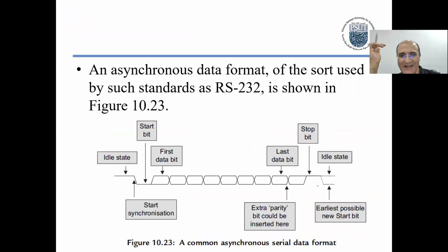So this is a standard. We call it RS-232, very common in asynchronous serial communication. Usually the line is pulled to idle, and then these are logical levels. Sometimes they can be flipped: the high could be low voltage, and the low is high voltage. You don't care about it for now. So usually you have a pin.